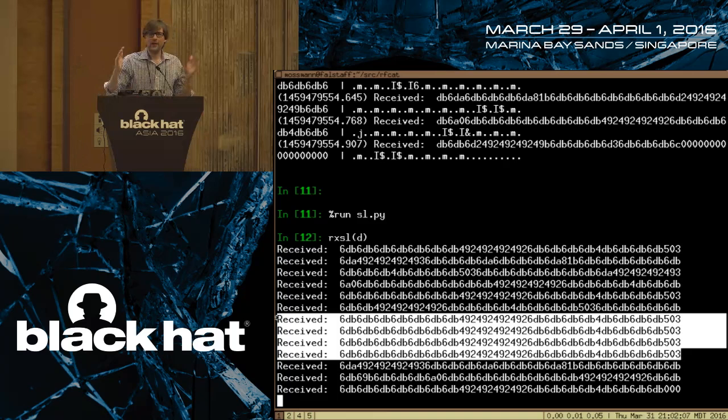Those all line up perfectly together, which is a good indication that they're lined up correctly. But some of these other lines are off by a little bit. So since I have the luxury of this thing transmitting a whole bunch of the same packets at a time, I'm just going to ignore the ones that don't synchronize, right?